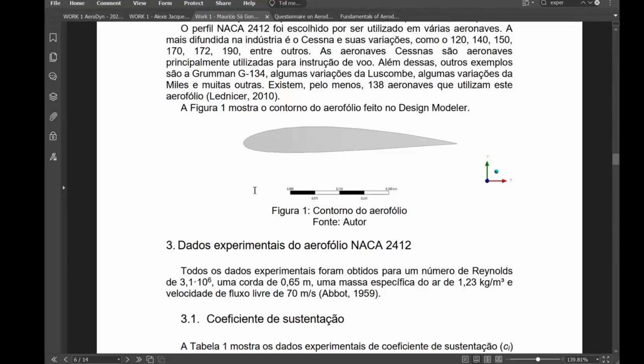But you need to show, like figure 1, how your airfoil will look, because in several cases you can have problems to draw. And I recommend you already make it inside Design Modeler or inside SpaceClaim or inside Discovery, a new tool for geometry design in ANSYS since 2022. You need to show it, because sometimes there can be a problem to visualize. So if there is a visualization problem of such an airfoil, you need to pay a lot of attention, because it will impact directly on your simulation.